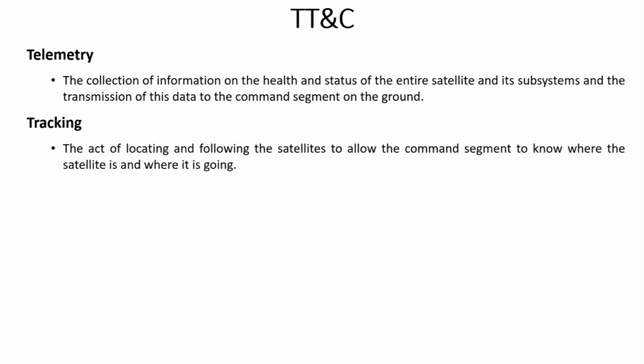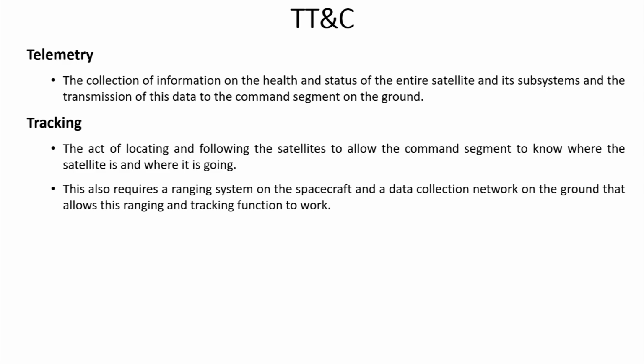Now, what is tracking? Tracking means to know the location of the satellite. It is the act of locating and following the satellite to allow the command segment to know where the satellite is and where it is going. This part we can know only when we have the tracking facility in our ground system, and we also need a receiver on the spacecraft.